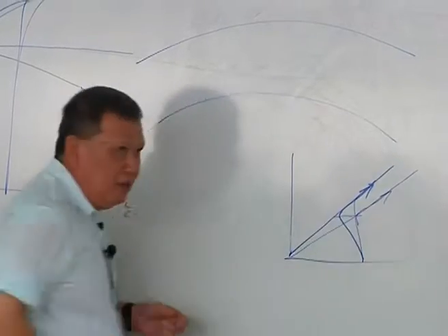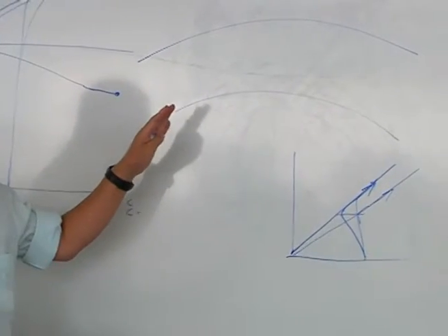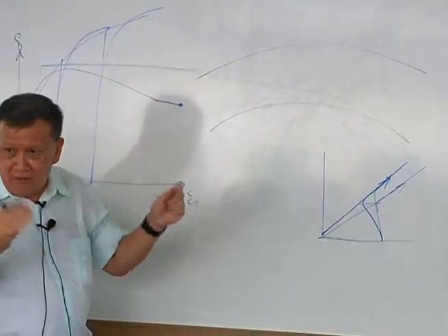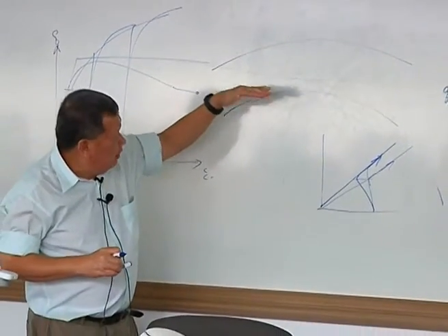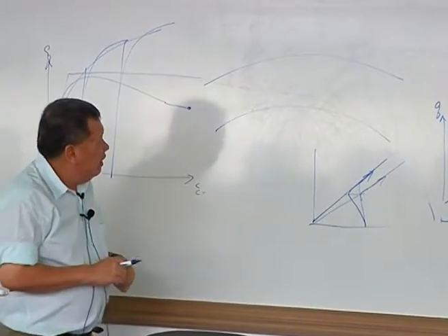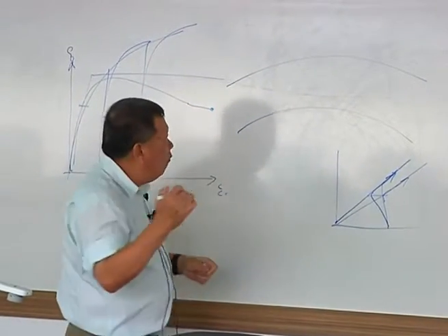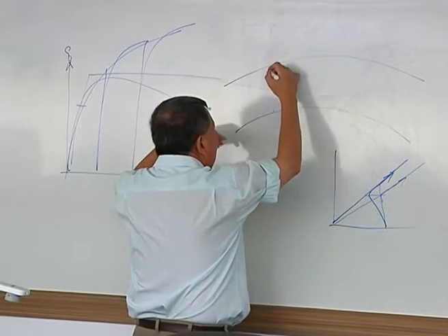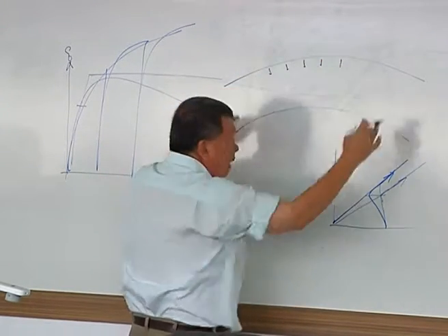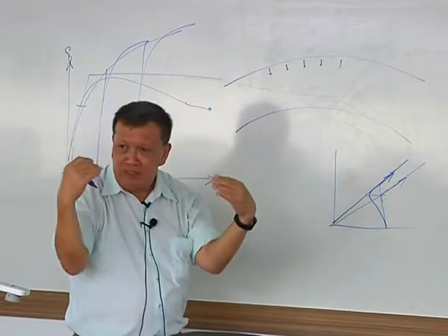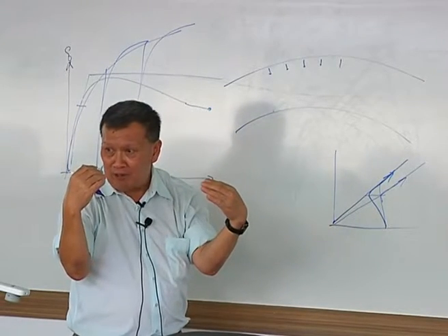And when you think about it, I'm just exaggerating it, but this is actually quite gentle. All right? This is plan view, looking down on the wall. Now, supposing you have a wall on this side, the north side, coming in, then the wall line will be placed into compression because your radius is decreasing. So it's compression.